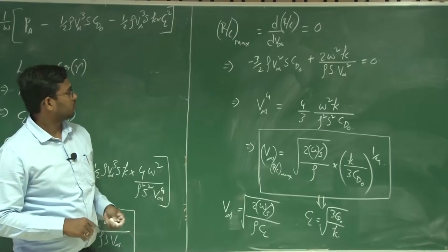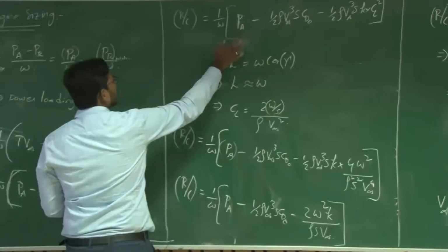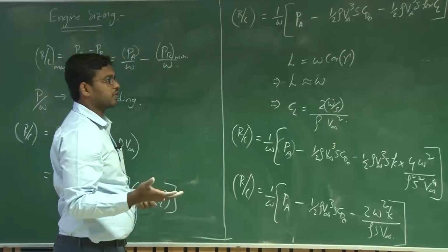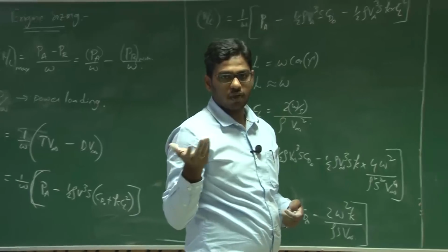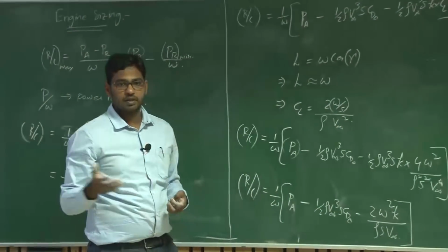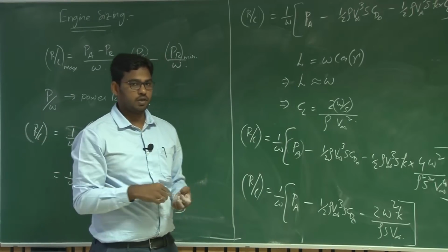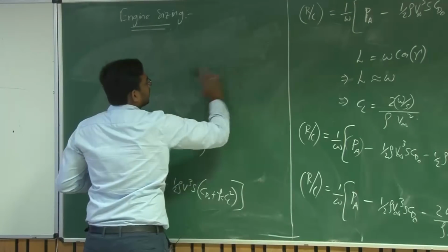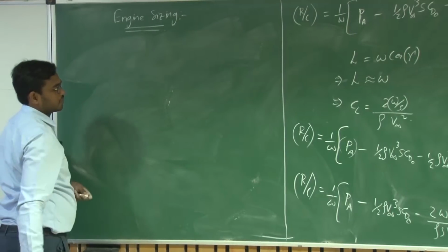So, if we rearrange this equation and understand that power requirement, you pick up the maximum power requirement of the total flight envelope, and then correspondingly with an efficiency factor select the power plant, right. What you need to take as an input is this rate of climb, for different rates of climb.